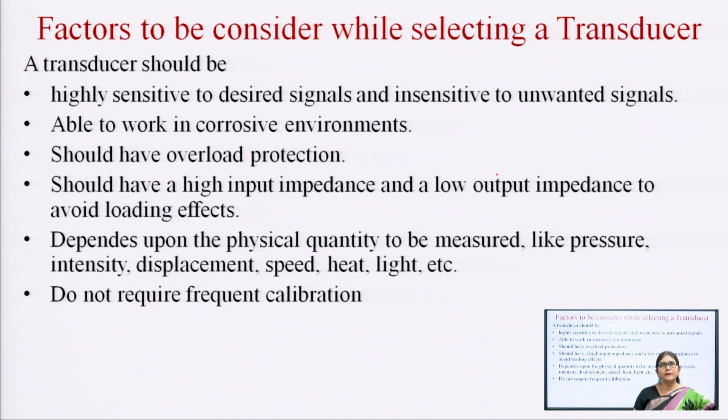First, it should have high sensitivity. Sensitivity means the change in output per change in input, so it can sense a very small change in input. Then it should be able to work in a corrosive environment.